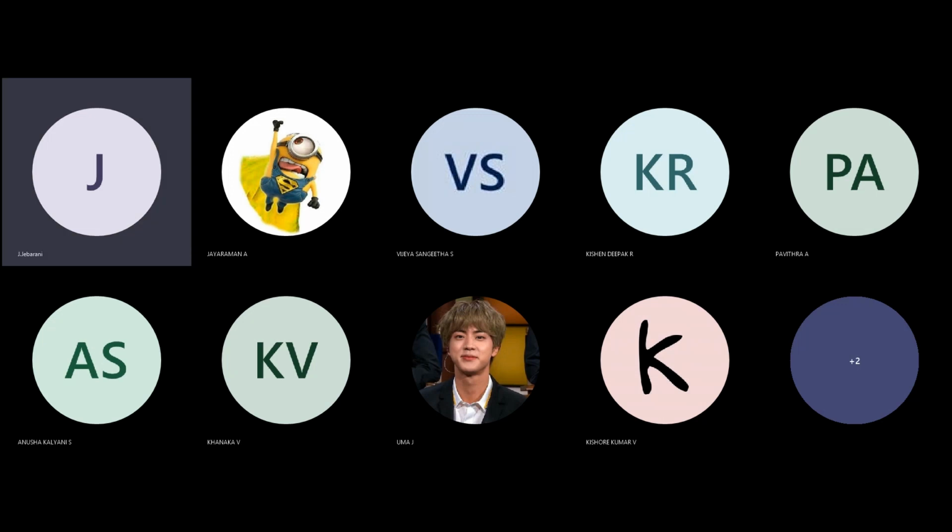In this short shot process, first the mold cavity is partially filled with polymeric material. After that, the water is entering into the mold. In this case, the water entry point and exit point are both maintained at the same location. So the water flows inside the molten polymer to push the molten polymer till the end of the cavity. Due to this, the polymer is well formed and completely fills the cavity with the help of water.